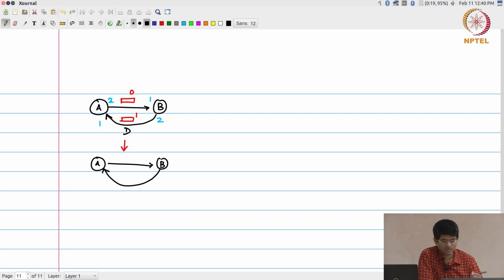So right now in the original state, A is ready to execute because it has one token sitting on its input, and according to that blue number written below A, it requires one token on input in order to execute. What happens when it executes? It consumes that one token and generates 2 outputs. So I have 2 tokens sitting on that output FIFO and 0 sitting over here.